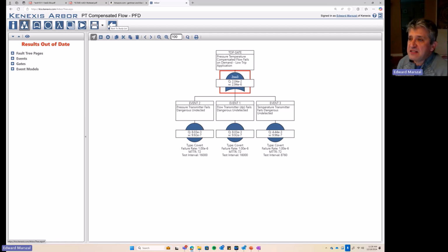But the reason it would be systematic is before that technician created that failure, that technician could have been sent to any PLC in the plant and would have systematically caused that trip. It's just that after they caused the trip, now there was a paradigm shift in the procedure that they're using. But their mental model that caused that failure was systematic.